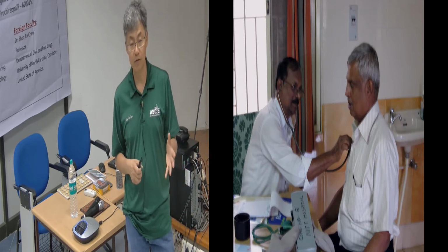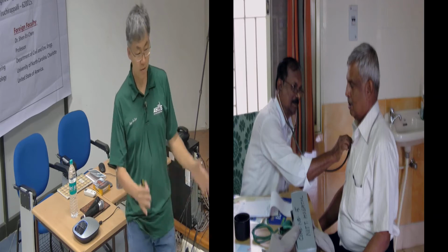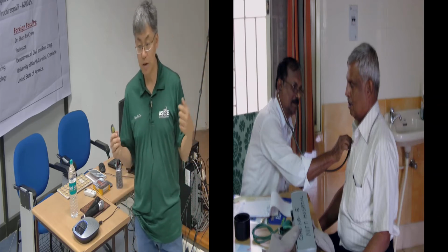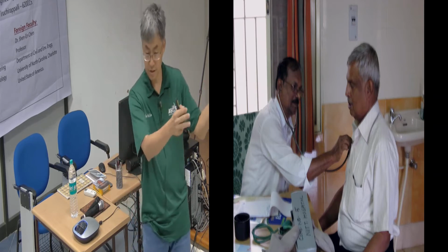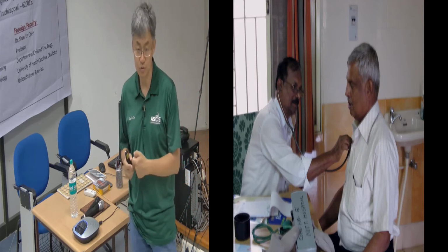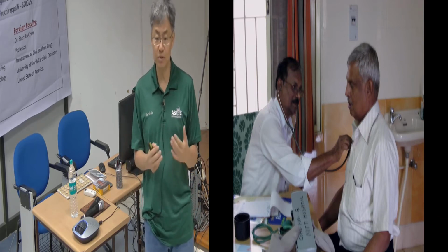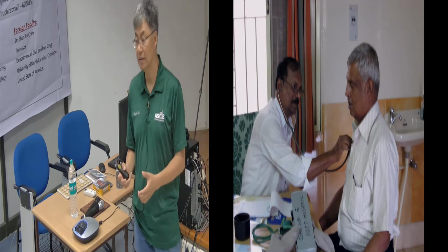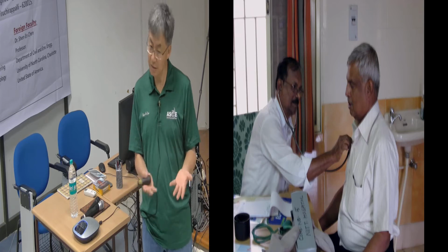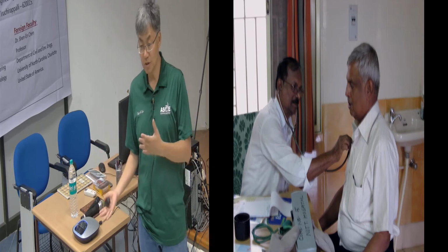Okay, so one of the arguments that I was involved in was a case in Taiwan. They have a tunnel, and the tunnel has a groundwater problem. The tunnel had some collapse, and it was due to groundwater effect. So this company suggested using ground penetrating radar to do the inspection. Well, anybody who's in NDT knows that ground penetrating radar cannot see through water. So what is that technique applied to? It's totally useless. But the consulting company doesn't understand that.